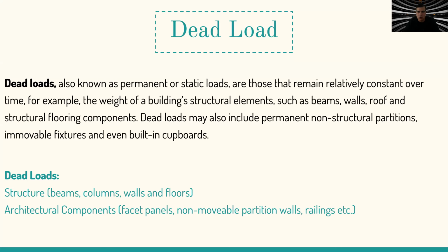Let's go with dead loads. Dead loads are also known as permanent loads. They are statics. They remain constant in the building. It's, for example, the weight of the building, every element of the building, from the walls to the doors that are fixed, the beams, the columns, etc. Everything that is fixed in the building.